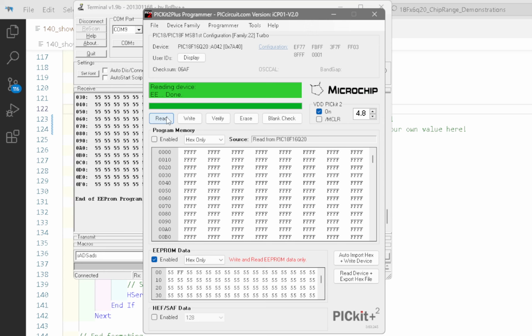Oh, I know why. Timing. That's interesting. That's a timing issue. Turn the power off. Read it. Okay, the issue there is because it was bouncing on the power, and it was erasing the chip in the few seconds it had, the milliseconds it had. And by turning the power off and reading it in, it's actually not rerunning the whole program.